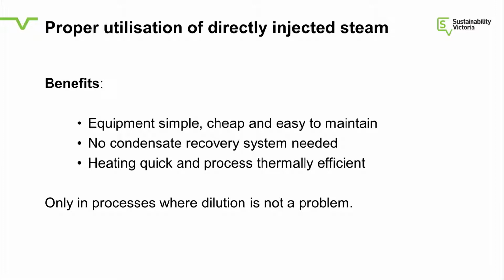As I said before, direct steam injection. This is where you put steam directly in with the liquid that you're heating to heat it. It's very efficient because all the energy transfers straight to the hot water. But it's important to make sure that you design it well so the mixer mixes with the hot water and doesn't bubble out and waste energy flashing off the top of the tank. You'll soon see it. You'll see a whole lot of vapour and bubbles coming off the top of the tank. That means your injector is not well designed, so you need to redesign that little steam ejector so that you don't waste energy like that.